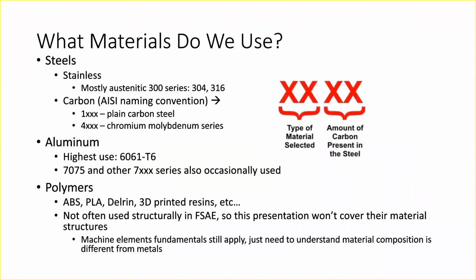Okay, so for the end of this, I just have a somewhat brief discussion on material selection. So most commonly on the car, you're going to be using some form of steel or aluminum, and in some cases, we use some polymers or plastics. So steels are really the most fundamental metal that you study in ME. So what you should recognize is that not all steels are created equivalently, right? A given steel, depending on its heat treat or other properties, the alloys that they put in it can have vastly different yield strengths. The thing that lumps together a given material is actually the Young's modulus.